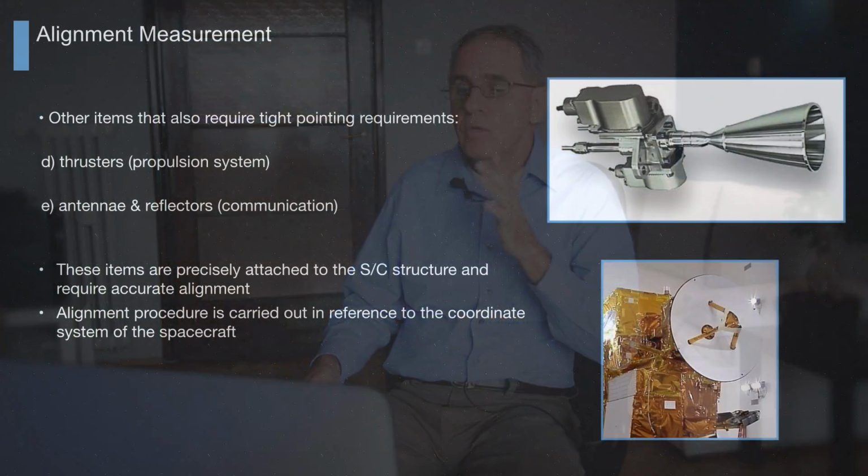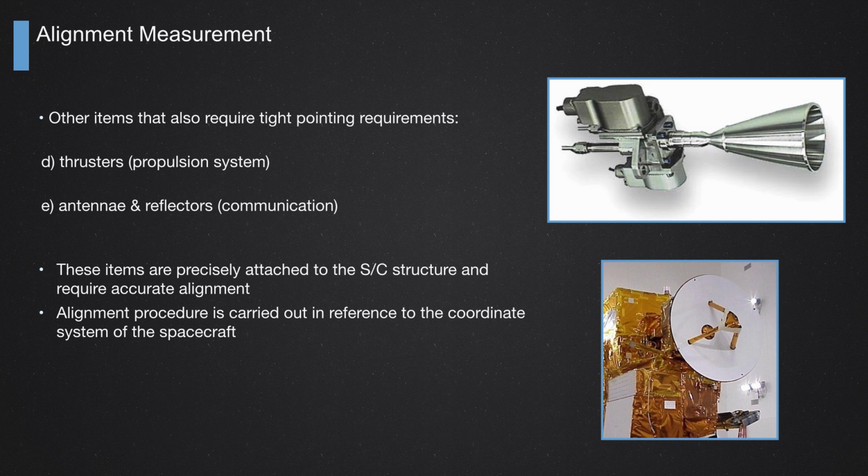These mirrors are connected to the sensors, antennas, or devices that require alignment. So we use three or four theodolites and do a kind of several-triangle analysis. We can tell exactly if those sensors and other instruments are installed in the correct expected position on the spacecraft before flying. So we make sure they are going to read the right position. So we use theodolites for this purpose.